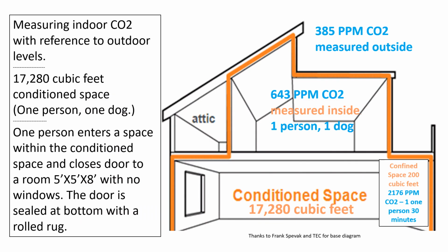Didn't seem like much of a test, huh? Well, I did it pretty quick. Total about 45 minutes in all. It took longer to edit and put this little program together. But we measured 385 parts per million outside in fresh air. Okay, we had 643 parts per million of CO2 measured inside with one person, one dog. We had a confined space of 200 cubic feet, and we had 2,176 parts per million of CO2 when one person went into that space for around 30 minutes.